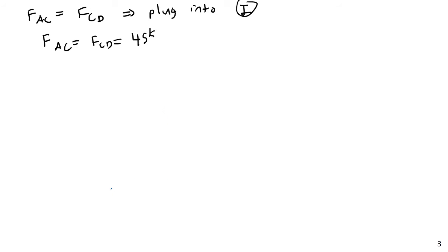I guess we still need to find the stresses, and we will need to make sure both of those are beneath or less than the yield stress, because we are making our entire analysis assuming elastic behavior. If this thing isn't elastic anymore, then we're going to have a problem. If it's beyond the yield stress, then our assumption will no longer be valid. And see earlier videos to see how you would deal with that.